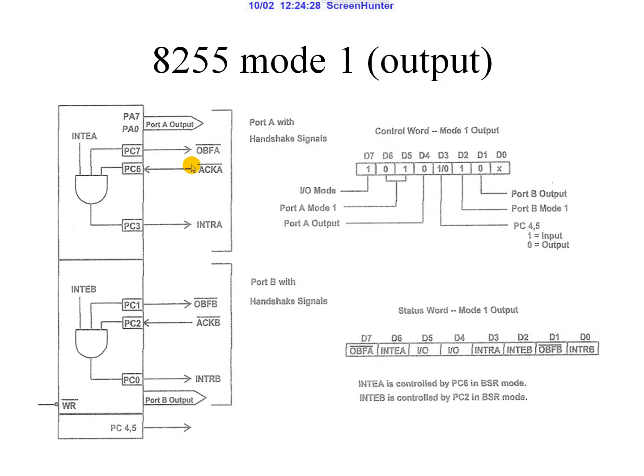That is why we are using the output buffer full. If the output word that is given from the 8255 to the external device fills that device's buffer, that particular thing is noticed on this port pin.